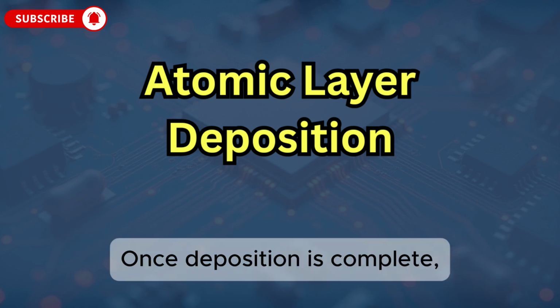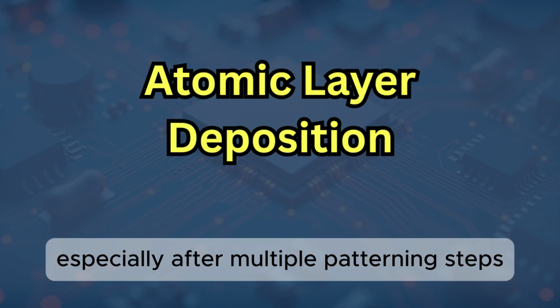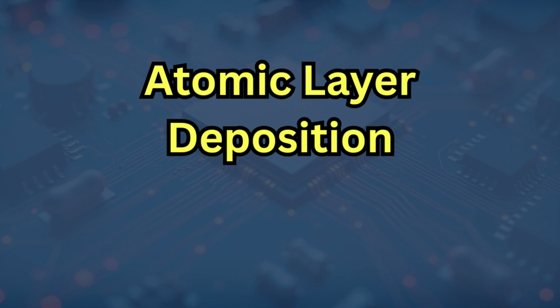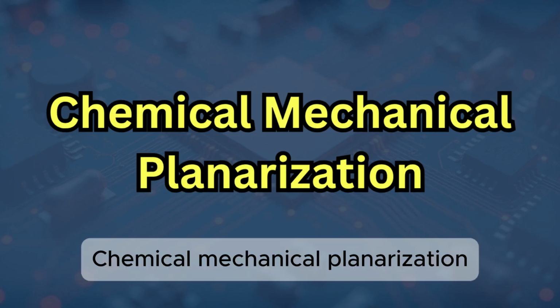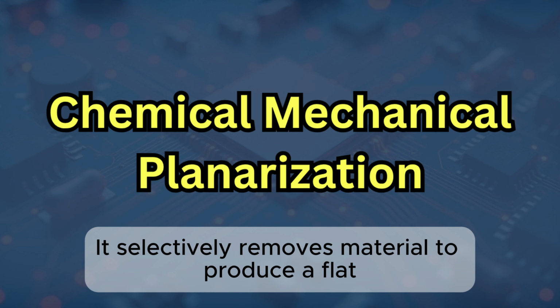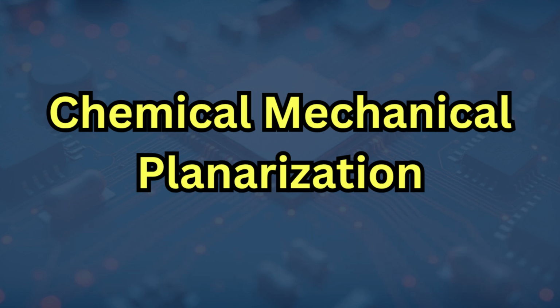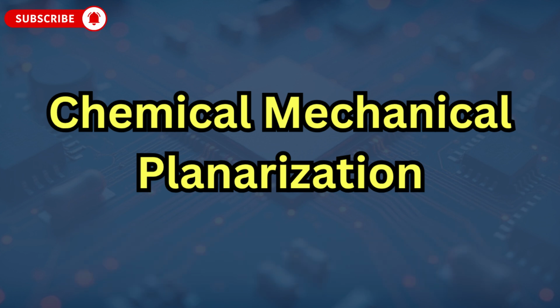Once deposition is complete, the wafer surface often becomes topographically uneven, especially after multiple patterning steps. That's where planarization comes in. Chemical-mechanical planarization uses a rotating pad and slurry containing abrasive particles and chemicals. It selectively removes material to produce a flat, smooth surface, crucial for multilayer lithography. Without planarization, depth of focus errors would stack up across layers, degrading yield and performance.